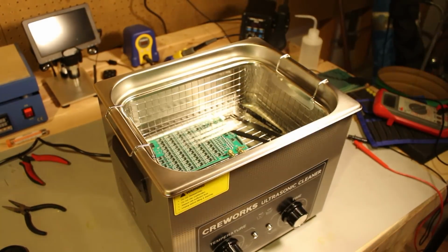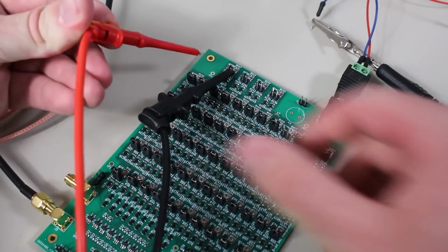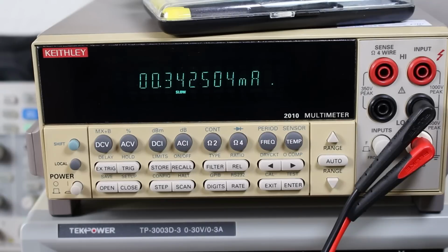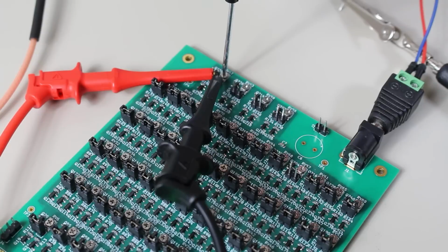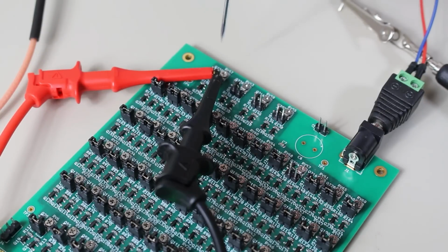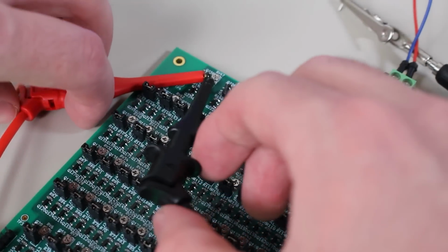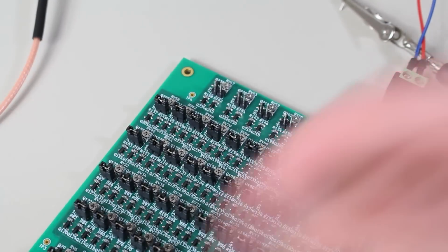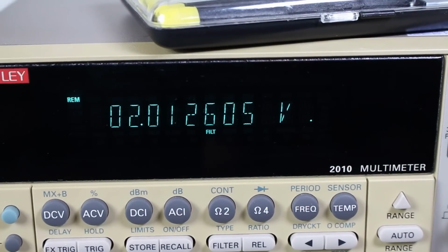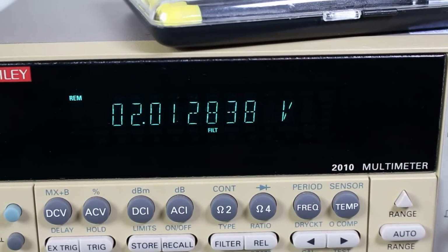The purpose of the headers was to allow me to calibrate the current sources by measuring them with my multimeter. Once the current was at its appropriate value, I connected it to the circuit with a jumper. This also took a while to get all the current sources at the correct values. But once I was done, I verified that the circuit was working by double checking that the output was buffering V low when all the inputs were 0. There was a bit of a DC offset on the output, but I figured that it could be trimmed later if needed.